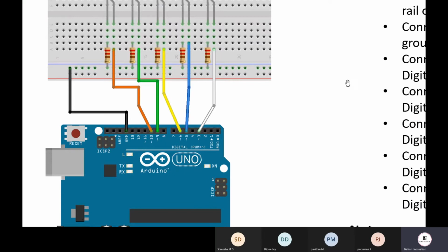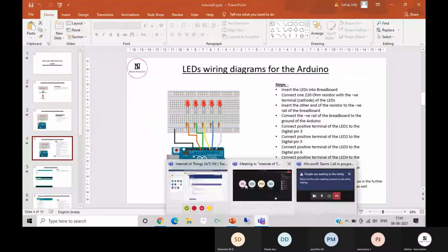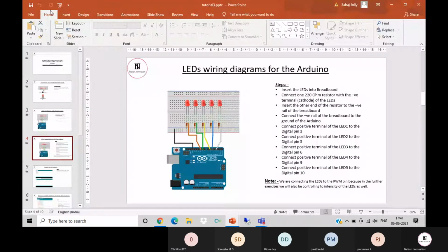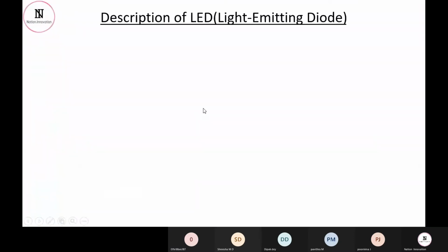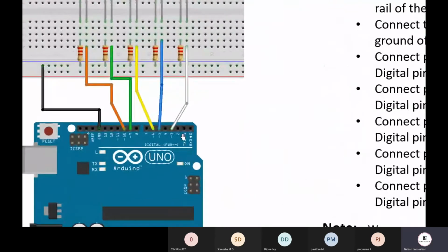to control that feature. And that is, in this case, just a second. So in this case, in Arduino Uno or the Nano, we have pin number 3, 5, 6, 9, 10, and 11 with the PWM functionality. Fine. And that is the main reason why we are using these pins only.